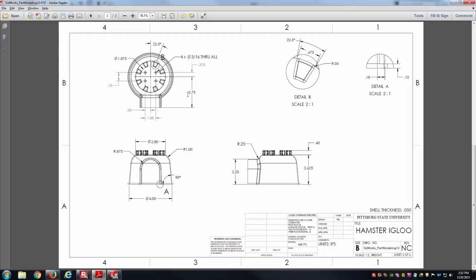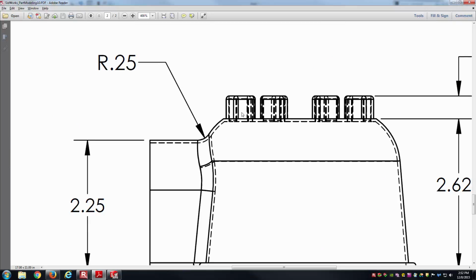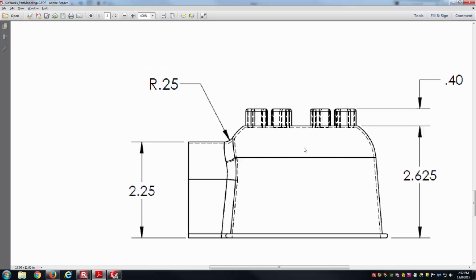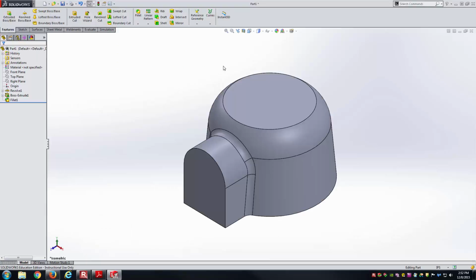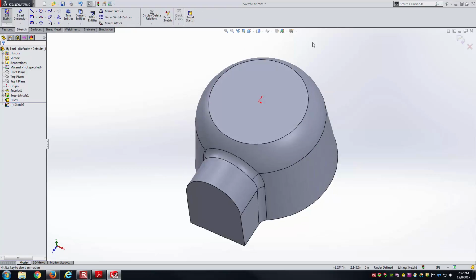So next, let's work on the extrusions at the top here. This pattern of 8 little extrusions. One thing you'll notice as far as when to shell, it's a little hard to see, but the actual hollowed out portions does go up into these pieces, and so I want to make sure I make these extrusion pieces before I shell it, or else these would be solid bodies on top of the hollow area. And so as far as the sketch plane goes, that'll just be the front, or excuse me, the top face, if you will. And so I'll just go ahead and make this sketch here.